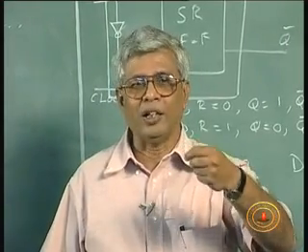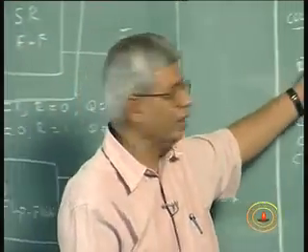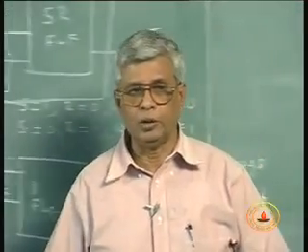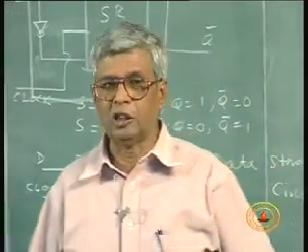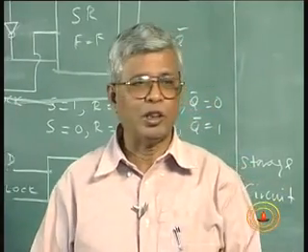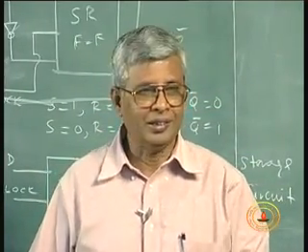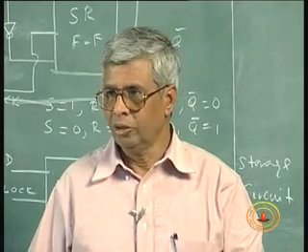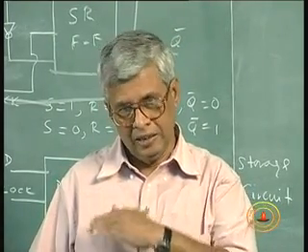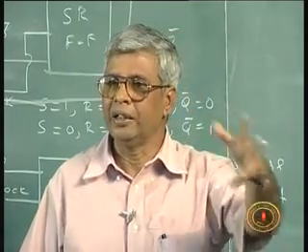But it is too small for us. Let us say 2 to 3 nanoseconds per gate, a total of 5 nanoseconds. Every 5 nanoseconds the output changes from 1 to 0. I can't do much with this, right? So I would like to have it change but in a more orderly manner, at more regulated intervals.